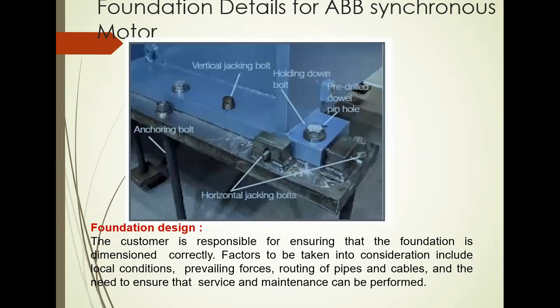Here you see foundation details of an ABB synchronous motor. Here we have the level bed arrangement. Some of the bolts here: vertical jacking bolt, anchoring bolt, horizontal jacking bolt, holding down bolt, pre-drilled down pin hole. So these are all the parts of that bed plate. It is above the ground level.